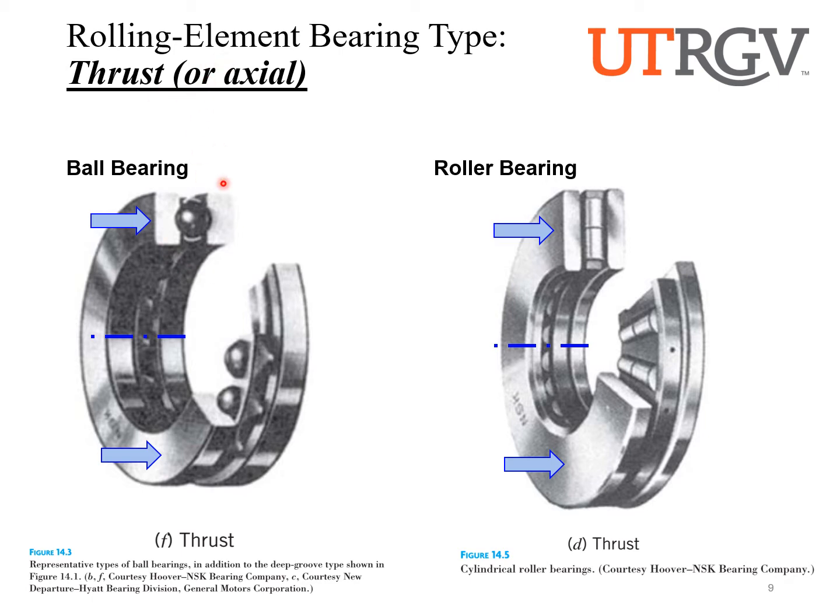Then it's a thrust bearing, sorry. So anyway, how do I do it? Look at the way the geometry changes. Now instead of having an inner and an outer ring, we have in this case what you want to call a right hand and a left hand. Anyways, we can see we can transfer a lot of load in that direction, no problem. And we can do it with the ball bearing and with the roller bearing.